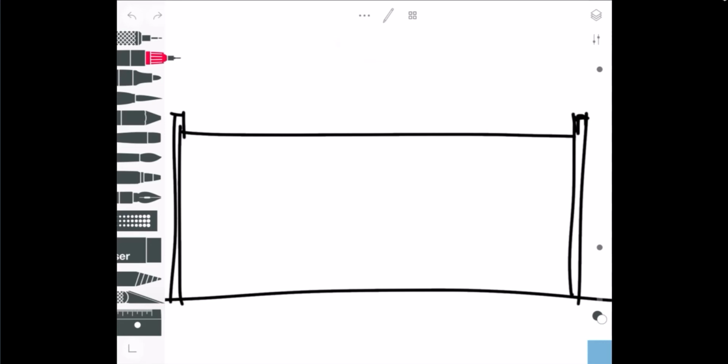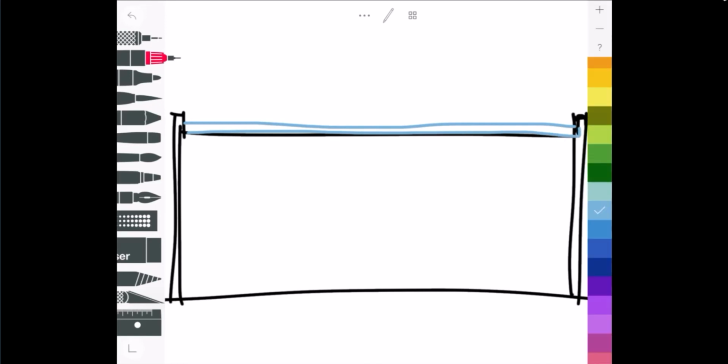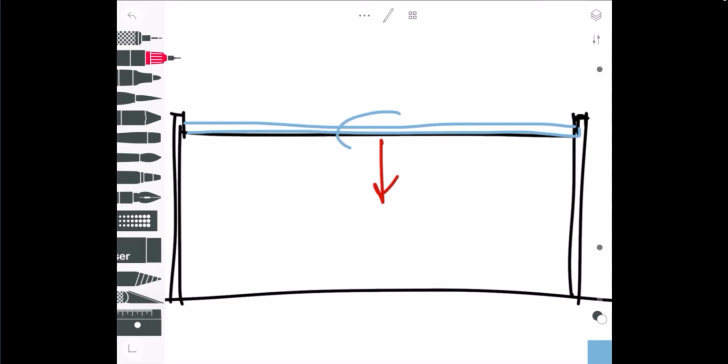So you're going to have a requirement for a base amount of insulation on that building. Let's just say that's that base amount. And we're going to drain this thing to the middle. So let's put a big red line here, and that's going to be the drain point in the middle right there. We'll get to how we're going to do that later. But if we were going to not slope the structure and just slope the insulation, we would still have a minimum requirement at the low point of that insulation, a minimum energy code requirement for a certain amount of insulation there.